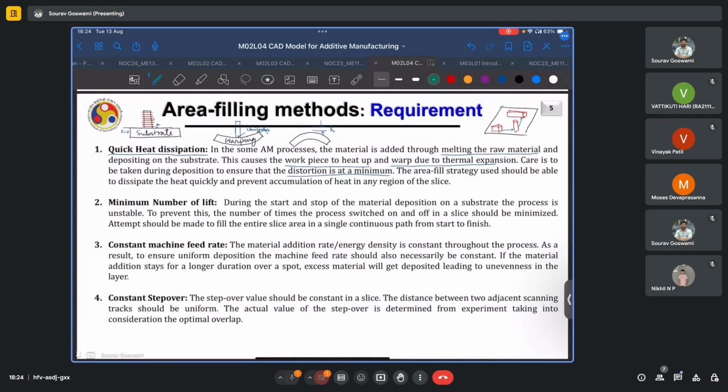These are called lifts. Why lift? Because often with such movement, the head might also move up from the build stage to prevent any collisions. And essentially, when we look at it, during such movements, we're not really depositing any material, and time is money. So these are often wasteful. If we can come up with strategies that minimize such lifts, then we'll be making maximum use of our time. The utilization ratio will be high, and our process will simply be more efficient.